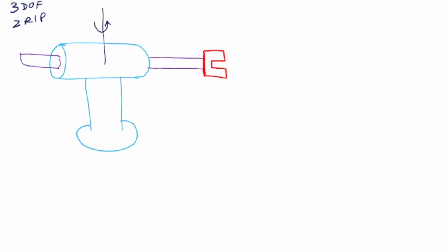Next there is a prismatic axis. The prismatic axis means it can move in that direction. So this link, which is marked with violet color, can go front and back. So this full link can come back like that, and that is the prismatic distance. So that is a prismatic variable. This is moving in a straight line, either to this side or back to that side. So that is my second variable, or the second joint.